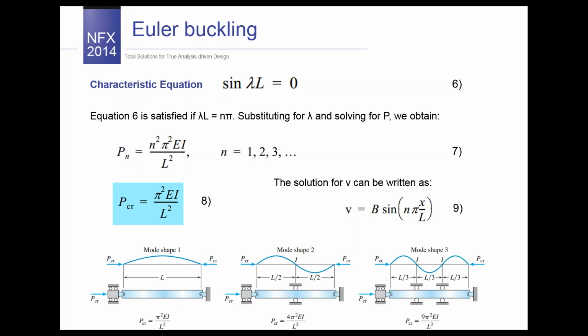It is an inflection point, and the magnitude of deflection at this point is 0. The curvature at the inflection point is also 0, which means the internal moment at this point is 0. And if we add rollers at any points other than the inflection points, the boundary value problem will be different, the eigenvalues will be different, and the solution will be different.